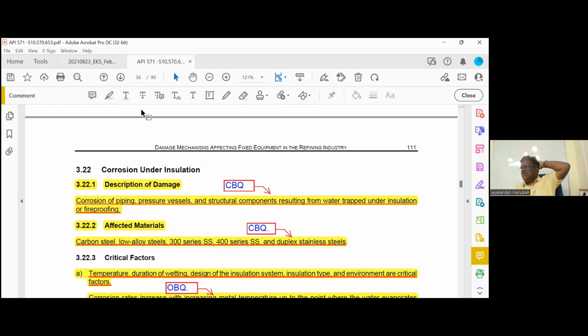These are the options. Now, where will CUI come easily? For example, a straight pipe versus a pipe with many branches, which is more affected by CUI? Many branches. And a leaking steam tracing on the pipe, or a pipe located downwind of the cooling towers. These will all have more CUI problems. Finally, coming to NDT, there are two types of NDT. How to check whether the insulation is wet or not?